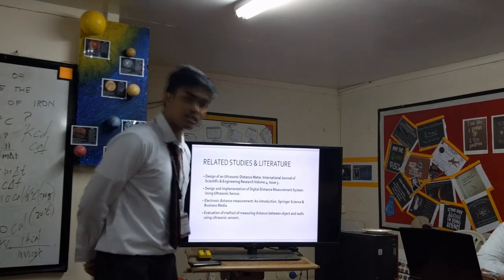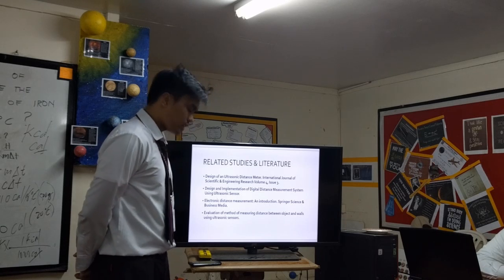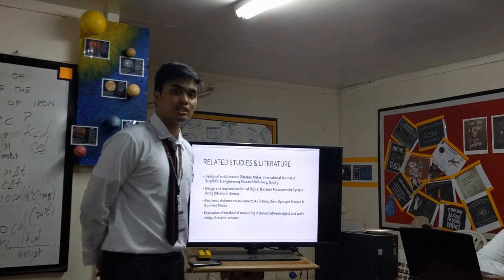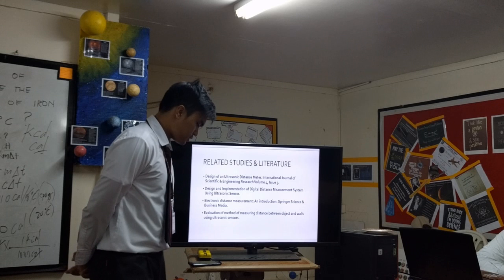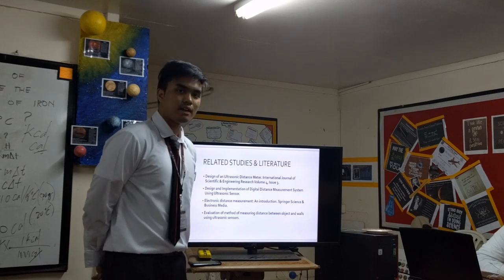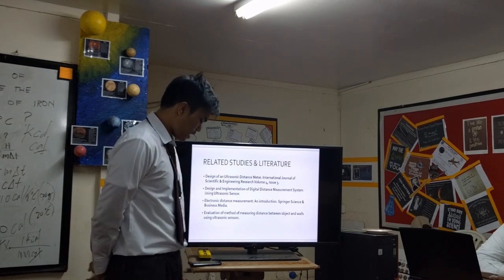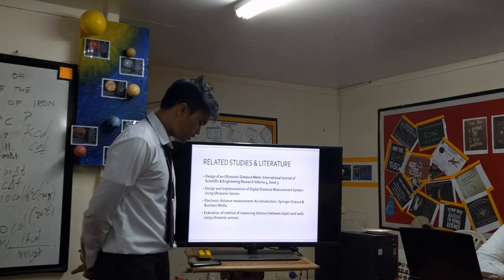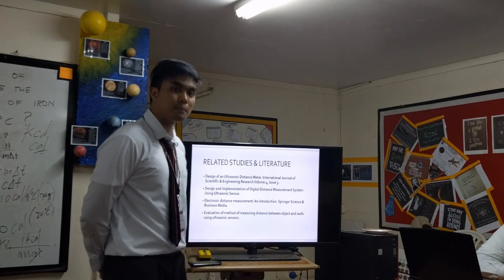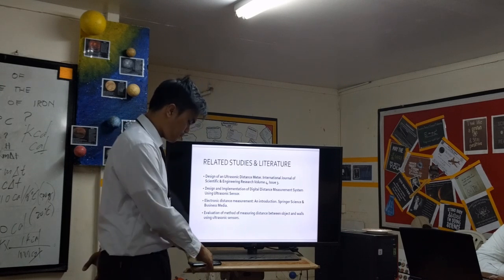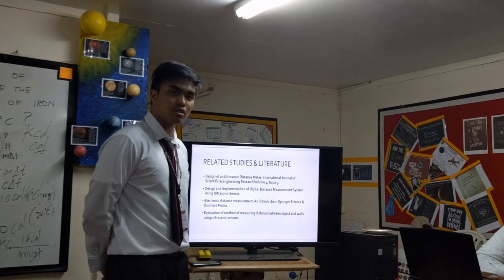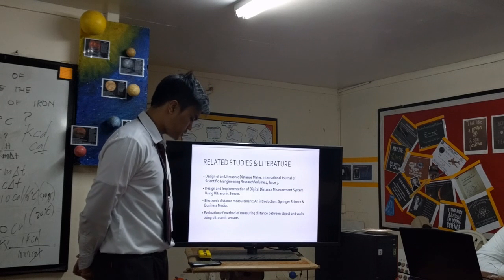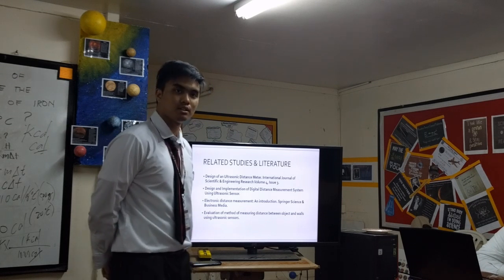The ultrasonic sensor that will be used by the researchers is the HC-SR04. The sensor has a transmitter that emits short, high-frequency sound pulses, which bounce off a surface and back to the receiver. This method of electronically measuring distance is known as the pulse method.